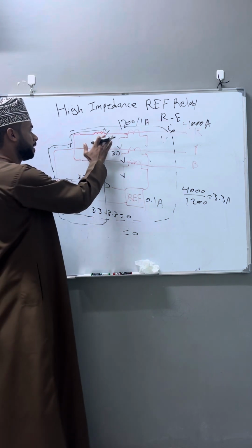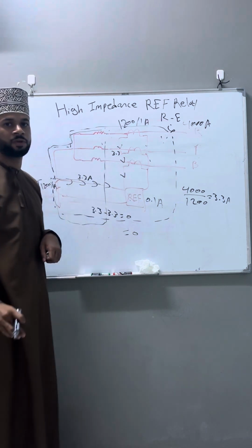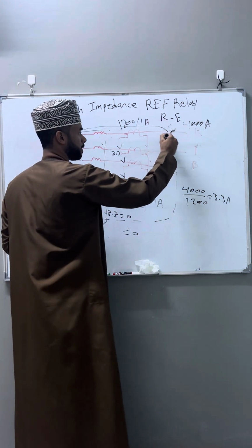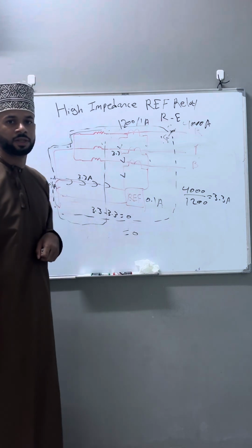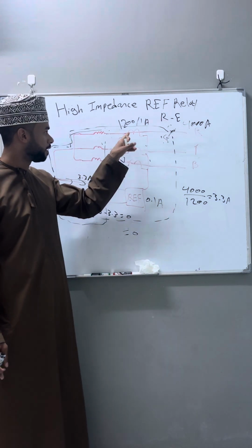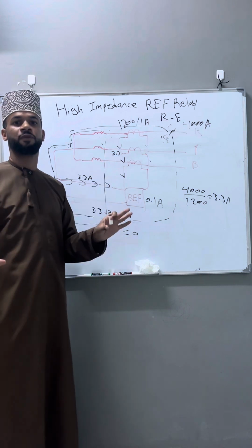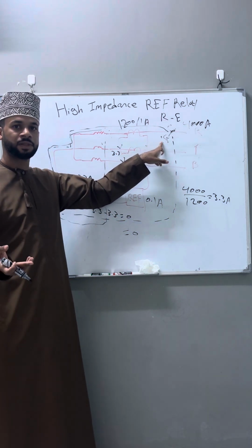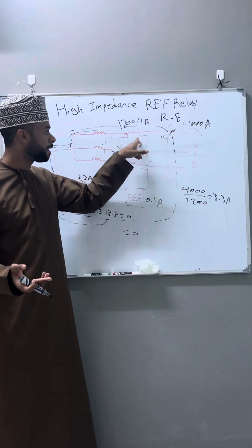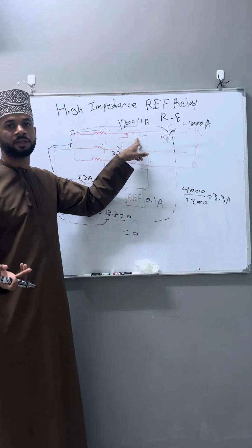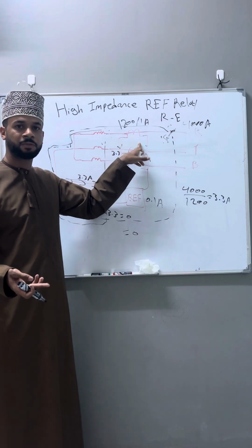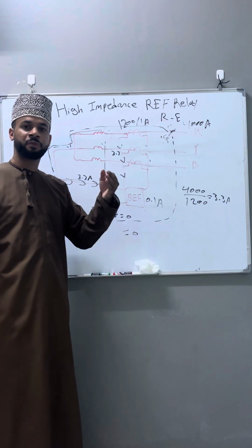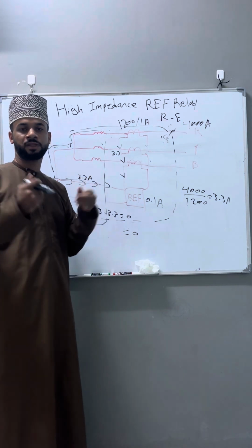Now let's study case 3, which is a very important case. Now assume the fault is an external fault, okay? Same external fault. Now assume, as you say, this CT and this CT will see the fault. But assume now, because of this high fault current, maybe this CT will be saturated. If this CT is saturated, it means there is no secondary current going to where? To the relay. So there will be no opposite current from the neutral CT.